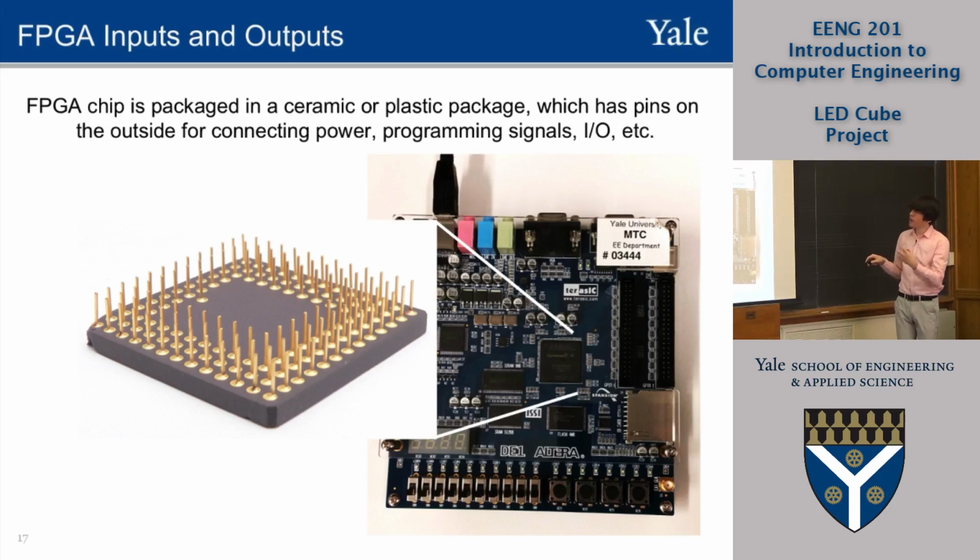If you took the FPGA package off the board, you would see either a ball grid array, or regular pins sticking out, and these have electrical connections to inside the chip. And then on the blue PCB board, there are little tracks of wires, some of which go from the FPGA chip to the GPIO connector.